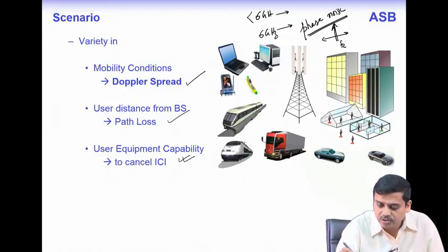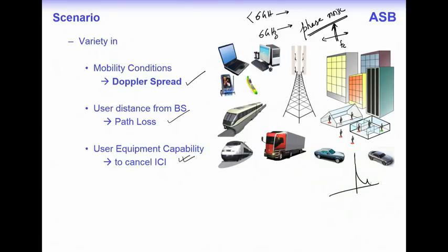So, in the frequency domain it is no longer a delta function; rather, you will find that there is a certain amount of spread in the frequency and certain other spurious frequencies that also come in. So, as you increase the carrier frequency, this particular effect dominates. Further, as you increase Doppler, we find that the Doppler frequency Fd is proportional to the velocity of the vehicle multiplied by the carrier frequency. So, simply, if the velocity increases, then Doppler frequency increases, or if the carrier frequency increases, Doppler frequency also increases further.